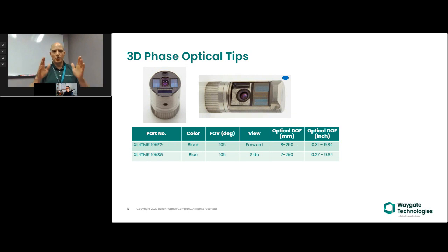They give a nice full screen, high quality image, and then provide measurement on demand capability with the structured light projections. And so a lot of our customers will do an entire inspection using these tips rather than non-measuring tips.